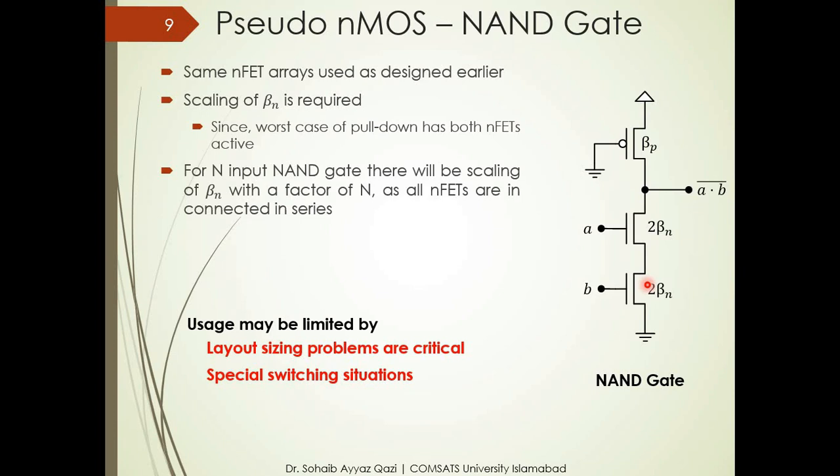The other problem could be special switching situations, because we have studied that the VOL value can be varied. So this might not be a perfect choice for this case. So we might avoid using the pseudo nMOS circuit in these two special cases.